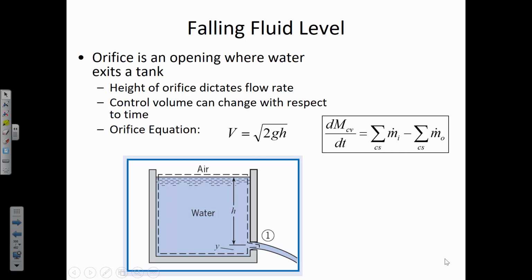Unless it's a very narrow pipe, the velocity that it's decreasing really will be pretty small. So it's not necessarily 0, but it's negligible. So we'd cancel out the velocity head term at 1. All we've got at location 1 is some energy above a datum, and so Z1.